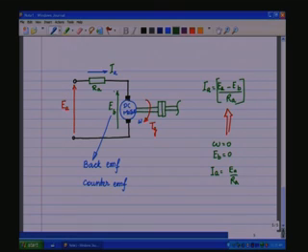And at no load, EB will be a value which is just slightly less than EA, and the differential voltage across RA will be just a few volts, and that divided by RA will be the IA. So, IA, the armature current, will have a very high value at startup and then gradually reduce to a value which is EA minus EB by RA.